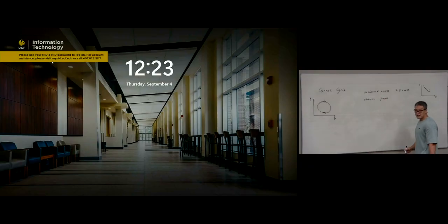So what's the PV relationship? P V to the gamma equals a constant, right? Correct, everybody? Gamma is what? Gamma is Cp divided by Cv, right? And how does this one look? It looks very similar to that one, but steeper, because we have the order of gamma here, so it becomes steeper. Okay, so this is the adiabatic line.